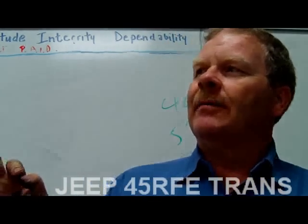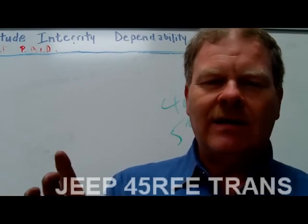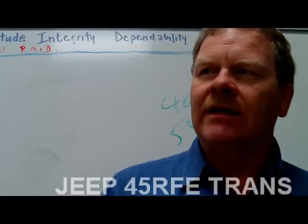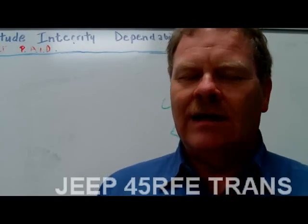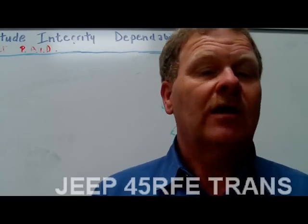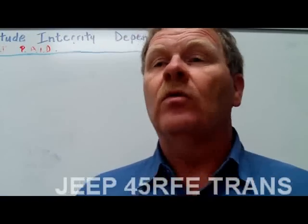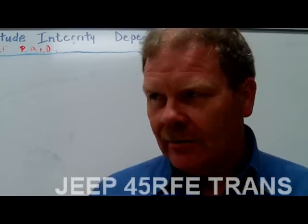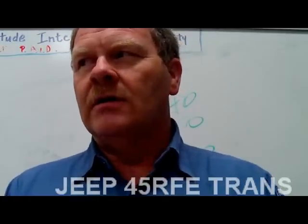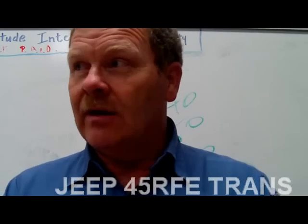But what we wound up with on that one was that little bitty transmission computer, a little tiny thing with a 49 wire connector plugged into it, one big wire and a whole bunch of little ones. And so I go in there and I look in the wire schematic and I find out, okay, power and ground goes in on this wire and this one, and I check power, got good ground. Okay, does it even know that the vehicle is moving because the speedometer didn't work? Of course, I also had a transmission computer that wouldn't talk, so I want to know if it's powered up. It was powered up. It had plenty of power and ground going to it.